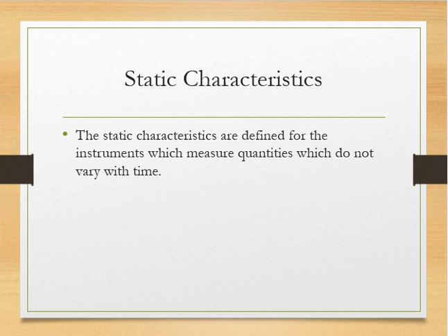On the other hand, the resistor is not storing any energy, it is just opposing the current. It can be called a static component, and you can easily analyze a resistive circuit, but it is more complex to analyze a dynamic circuit which uses a capacitor and inductor. Just like this, there are different characteristics based upon the same definition of static and dynamic.